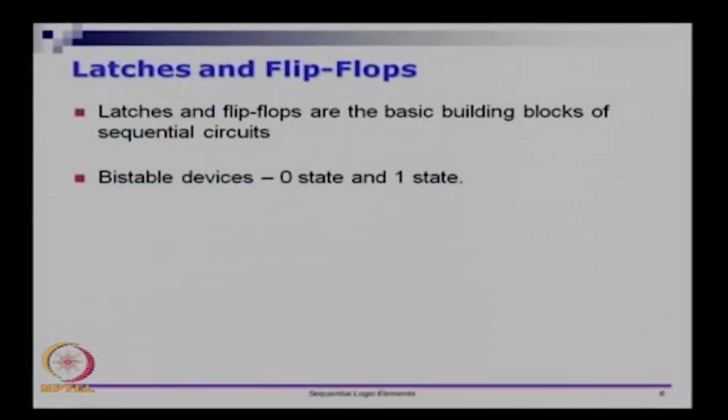So we need a memory element which can remember the value in some sense. Going back to the problem I gave, we need to remember the set as well as the reset given to the circuit. So we need something like that, and it has to remember. So these are the three things. To do this, we have different kinds of basic logic elements. Latches and flip-flops are the basic building blocks of sequential circuits. The first thing is that these devices, both the latches and flip-flops, are what are called bistable devices.